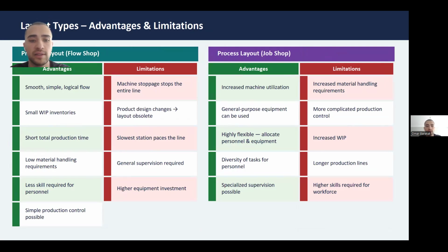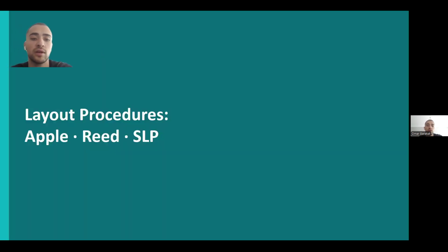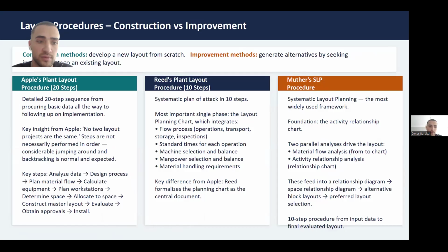These are the four basic types of layouts. There's product layout, fixed product layout, product family layout, and process layout. A critical difference to flag: in fixed product layout, the fundamental principle reverses. In every other layout, materials come to the workstation. In a fixed product layout, the workstation comes to the material. Boeing assembling a 777 is the canonical example. The aircraft does not move. The tools and the workers move around the aircraft itself. So, here are some advantages.